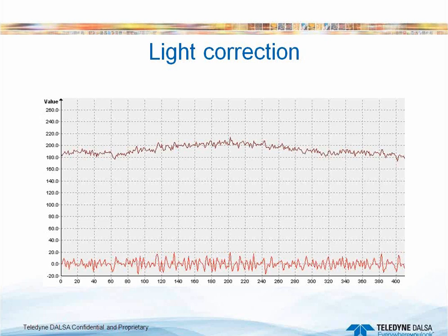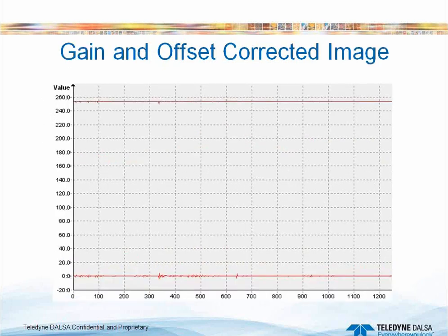So line scan cameras have what they call gain and offset correction. Because again, you're pretty much creating a lookup table. You give the camera a black object to get the offset, and then a white object under the lighting that you're going to be using, and you correct for flatness. After you execute the utilities provided by the camera, you will get a nice flat field correction. That's another terminology for gain and offset.